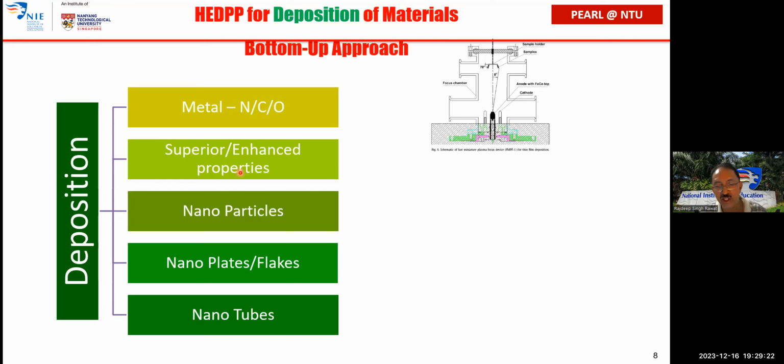And that in situ processing, we have done the calculation of the temperatures by solving suitable equations. They can exceed beyond the melting temperatures depending on the distance. So it is basically very high temperature transient annealing, which is not available even in the normal thermal annealing experiment. And the good thing is that here the annealing is done in the microsecond time scale. So you're not doing it for 1 hour, 10 hours, or 15 hours like what material people do.